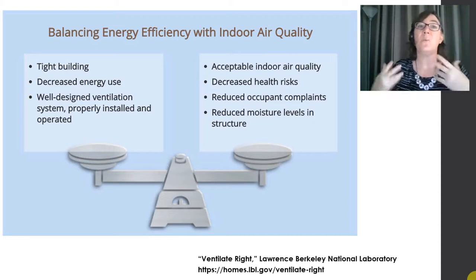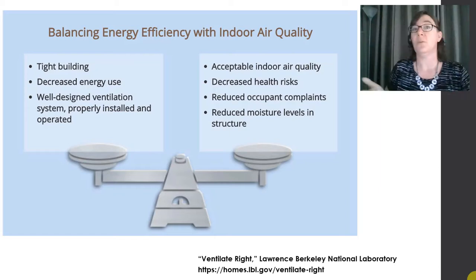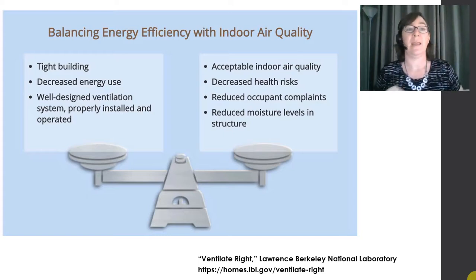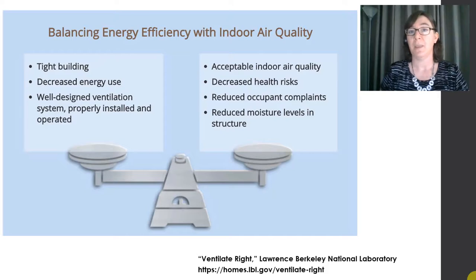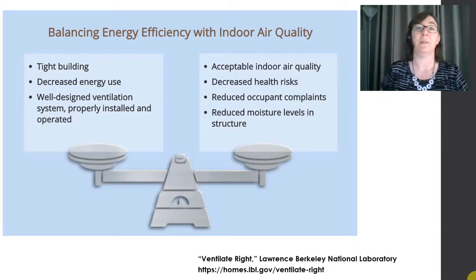So what do we do now? We know that we need to balance energy efficiency with indoor air quality. We still build tight buildings for their decreased energy use, but you also have to provide a well-designed ventilation system to provide that acceptable indoor air quality.